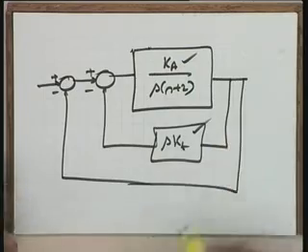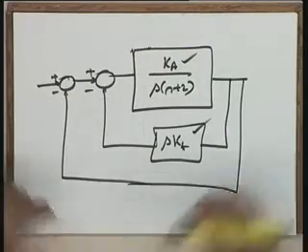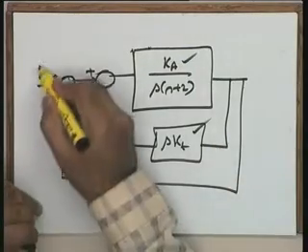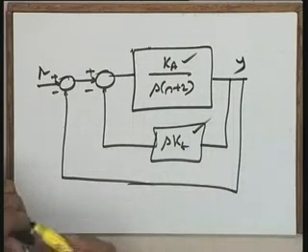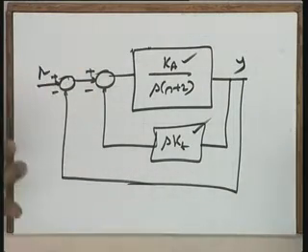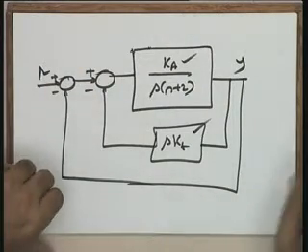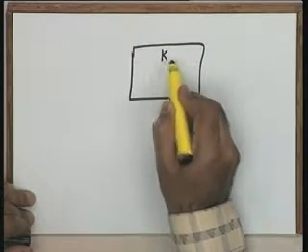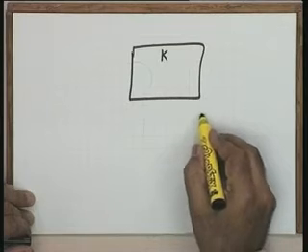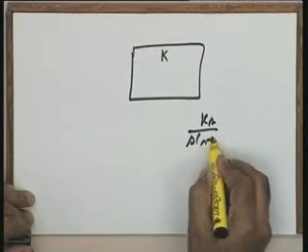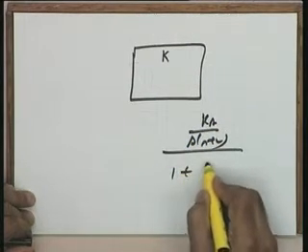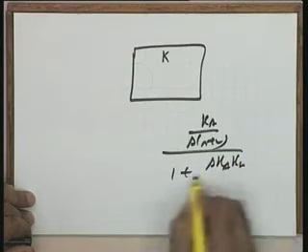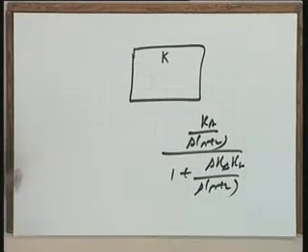So there are two variables I am taking, Ka the amplifier gain and Kt the tachometric constant, R here, Y here. I want to design this system for a specified value of zeta, for example. Okay. Resolving this into a single loop configuration, you see I can easily get this diagram. Please help me whether this is okay. Well, let me write it separately. It will be Ka over S into S plus 2 divided by 1 plus S Ka Kt over S into S plus 2.